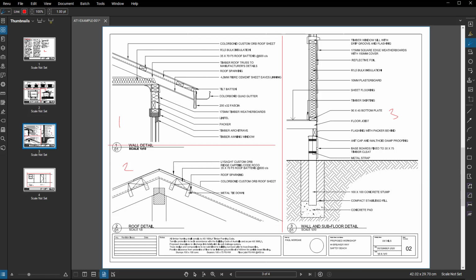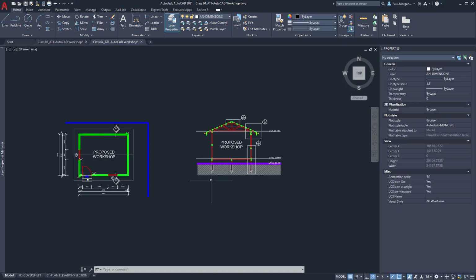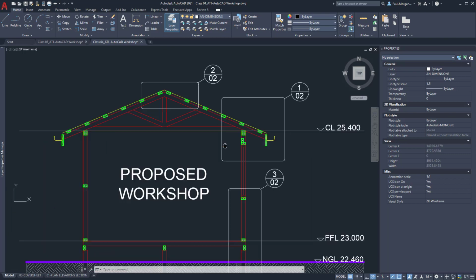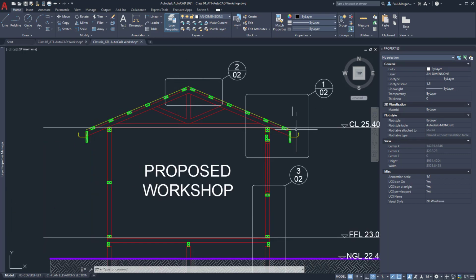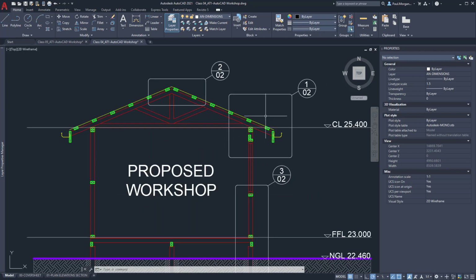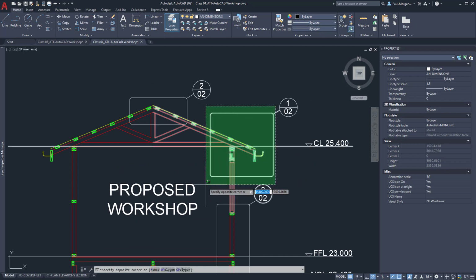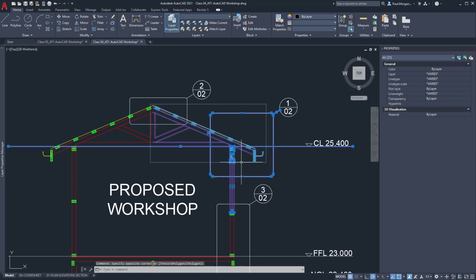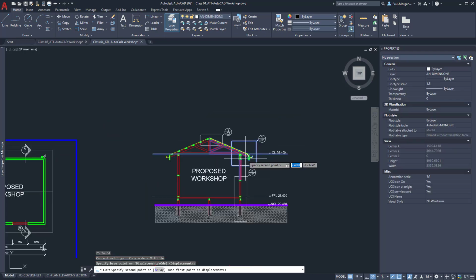I'm going to go into AutoCAD, into my file. By now you've marked out where you want your details, essentially, as per the example sheets. What I'm going to do here is nothing that intelligent about it. I'm just going to select everything that's around this box and copy it out to a different area.